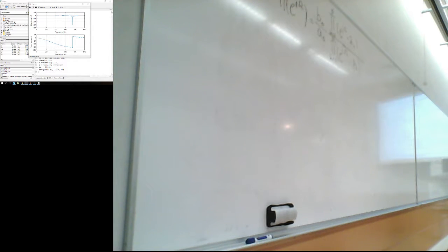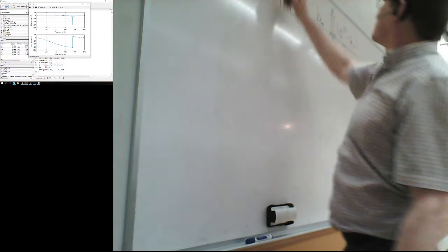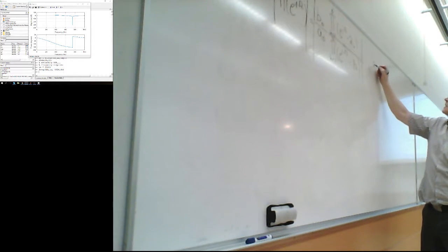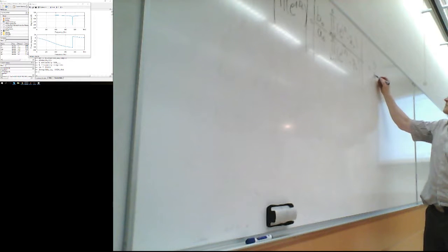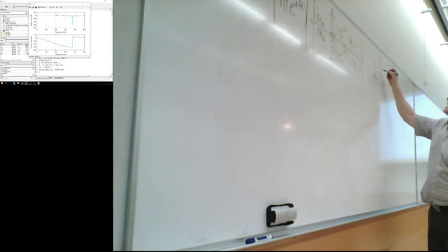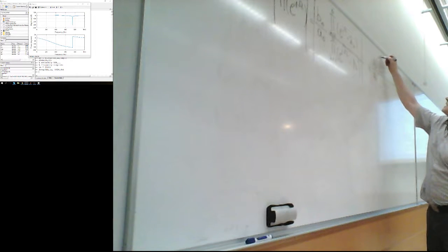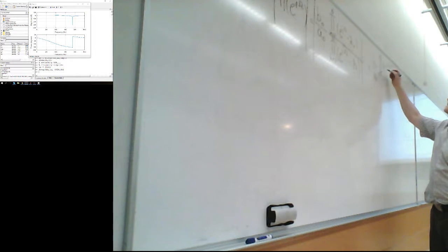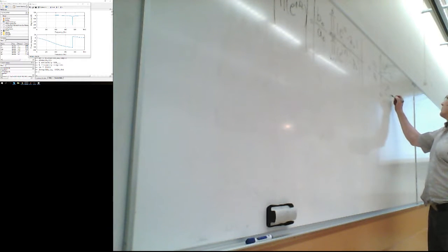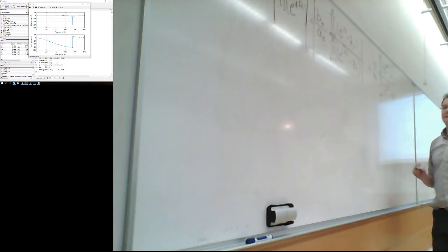Then you take the amplitude response: B0 divided by A0. On the numerator we have, k from 1 to n, the absolute value of e to j omega minus zk, divided by k from 1 to n, e to j omega minus pk. Good.